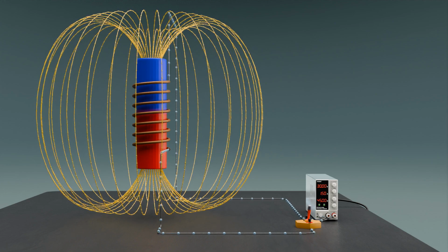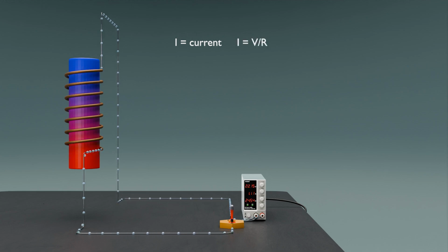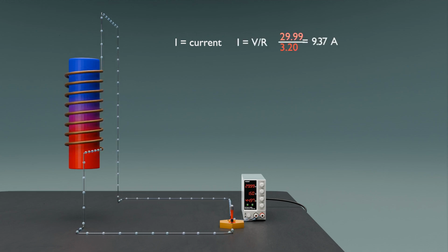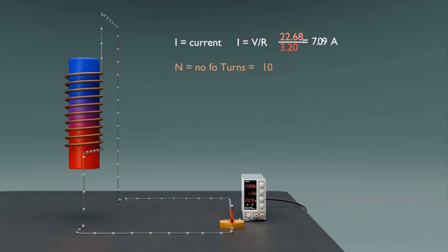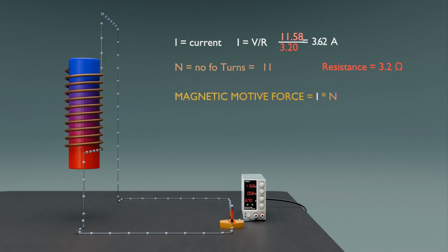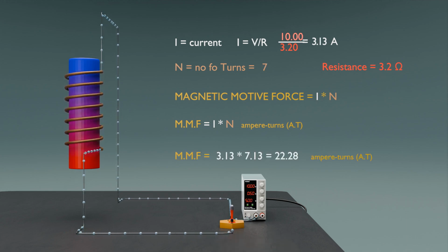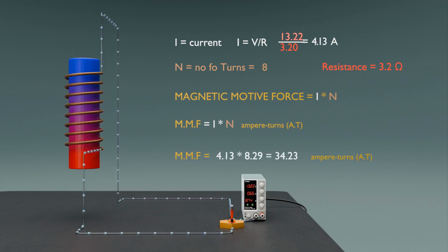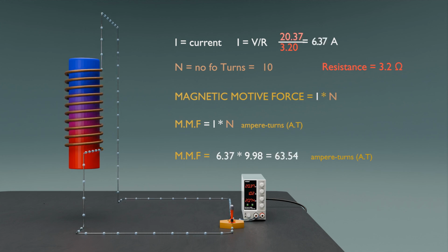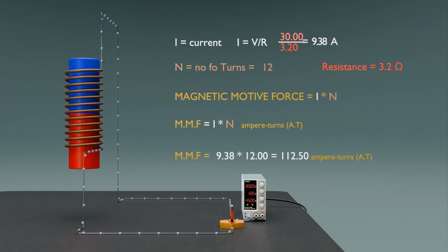We see the concept of magnetomotive force, or MMF, in the coil and the current, I, flowing through it. Mathematically, this is expressed as MMF equals Ni. The number of turns, N, refers to how many times the wire is wound around the core of the inductor. MMF is responsible for creating the magnetic flux within the inductor, illustrating how the number of coil turns and the current together determine the strength of the magnetic field.